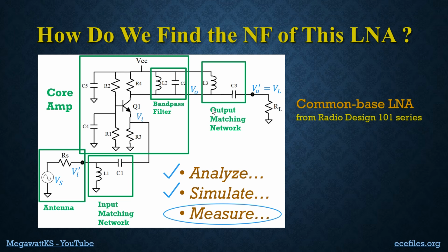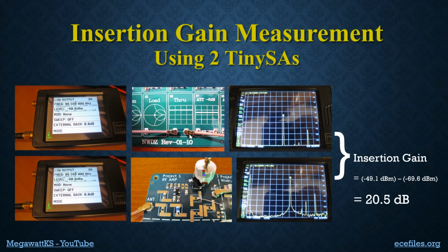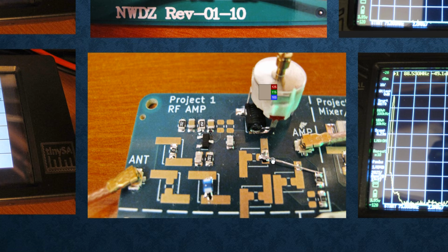And the amp I built is basically this one. It's not the one with the split inductors. So here it is, down here in the bottom center. I did bias it at 5 milliamps. Here's the 2N5179 transistor, or I think it's MMBT5179, something like that. And the bias resistors and so forth. And the LC tuned circuit is right here.